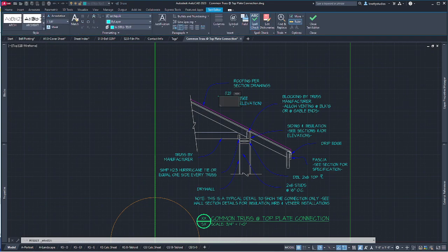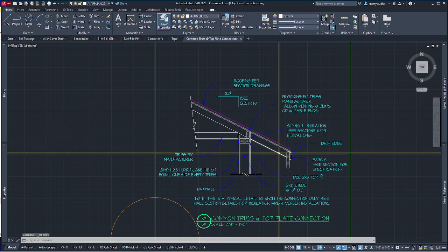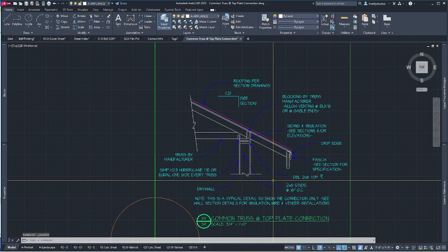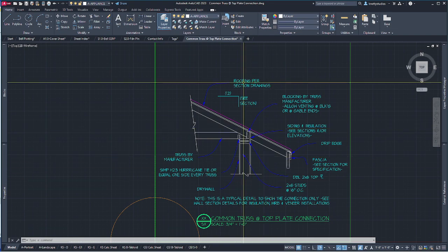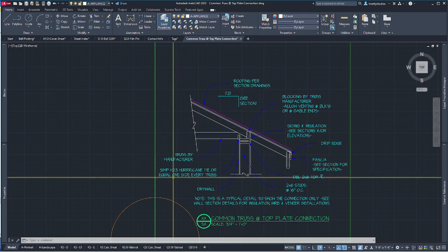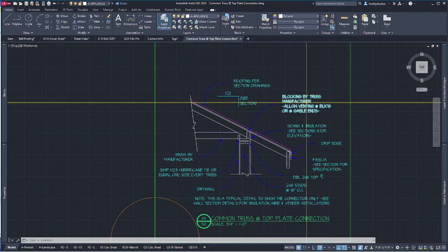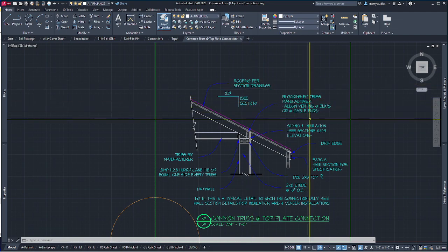And these days I've actually been putting pretty much all my technical information on the sections. So I don't like to have things repeated in a drawing, because if I ever have to go in and make a change, then I've got to change it everywhere. And if I miss it somewhere, I'm going to get a call during the build, which one of these is right. So there's a lot of reference to look at the section or look elsewhere for stuff.